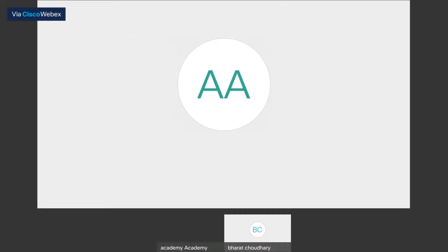And CMOS was in micron, it was in nano also, but only up to the 65 nanometer technology. After that came 45 nanometer technology with high-K metal gate, and below that 32 nanometer and 22 nanometer technology. So FinFET technology is better in terms of performance, and it is leading to a lower cost also, because of the mass production.